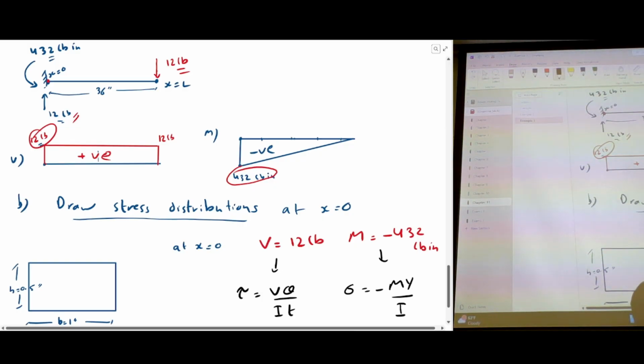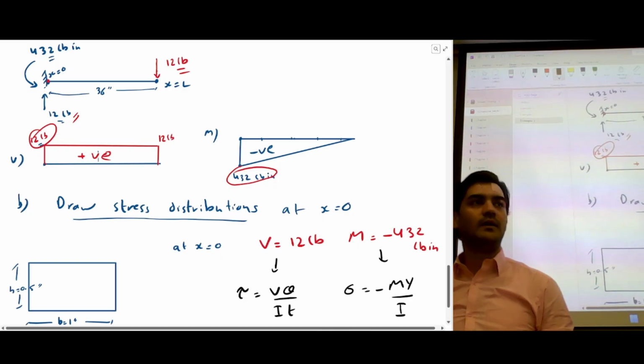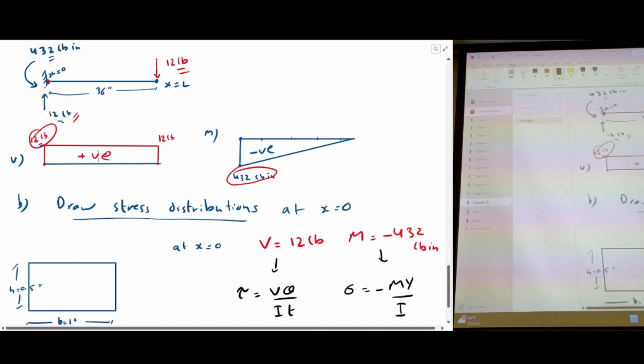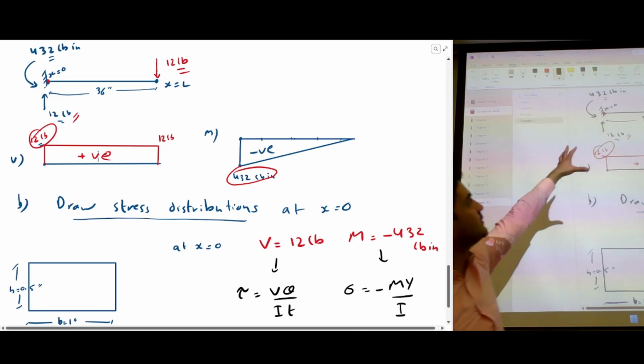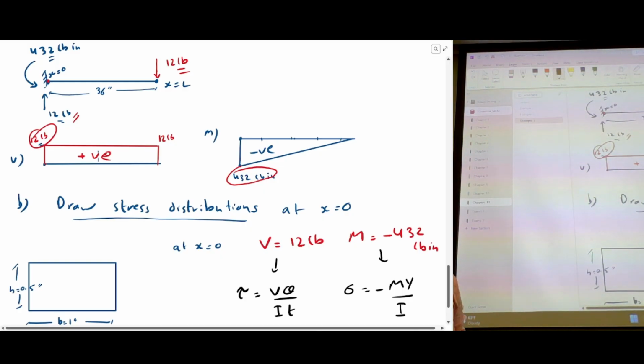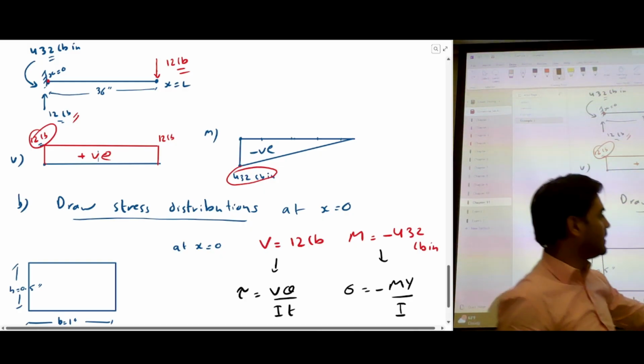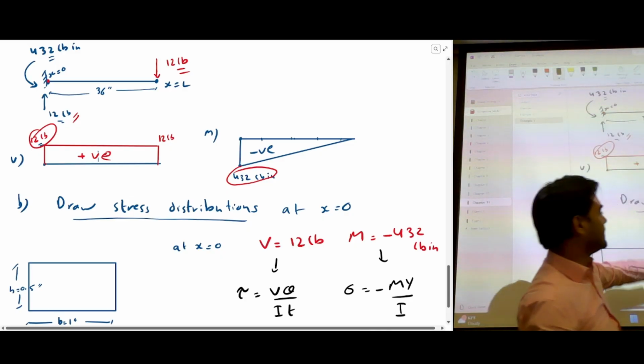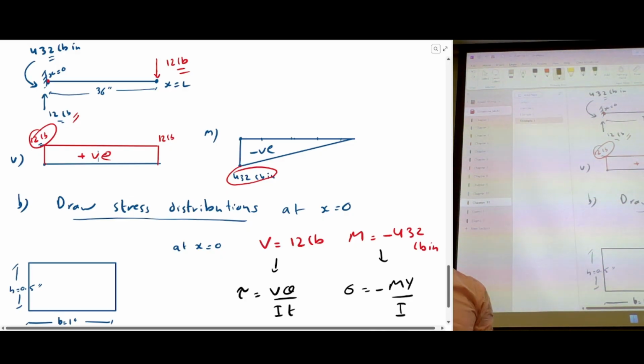Once we get these stresses, we can extract the stress element, and from there you know what to do: calculate the maximum principal stresses, compare them with the yield criteria, and figure out if this condition will cause yielding or not. So you can try to calculate the stresses along the cross section and draw the distributions like you used to draw before. But you understand the flow, right?